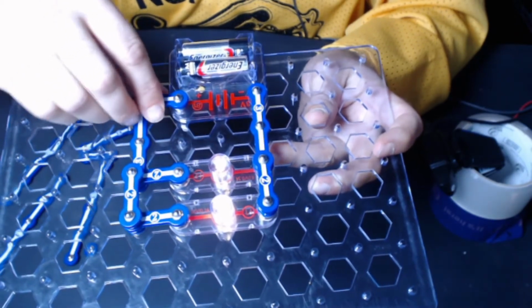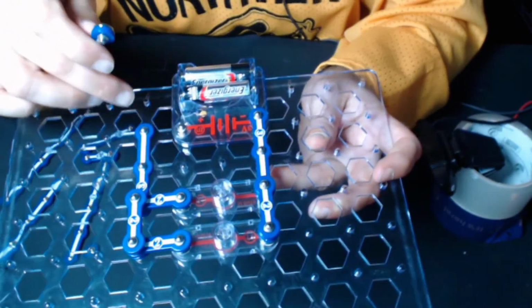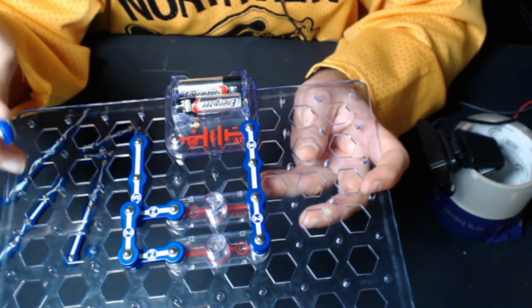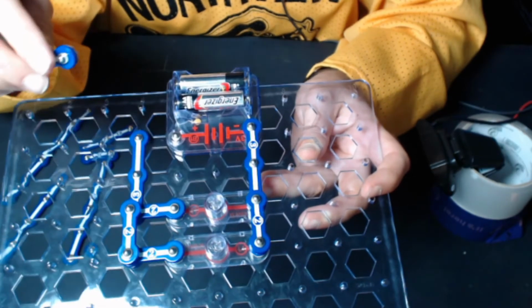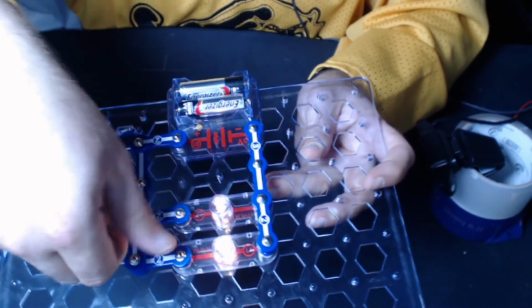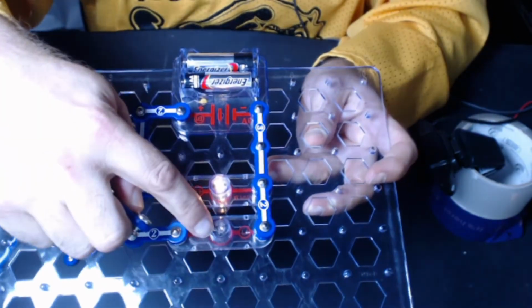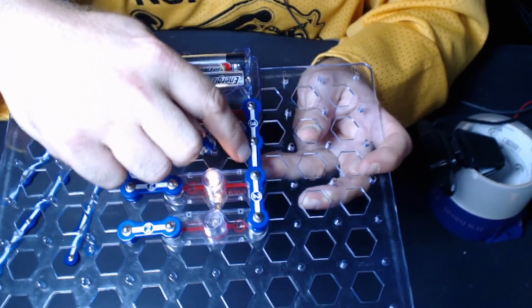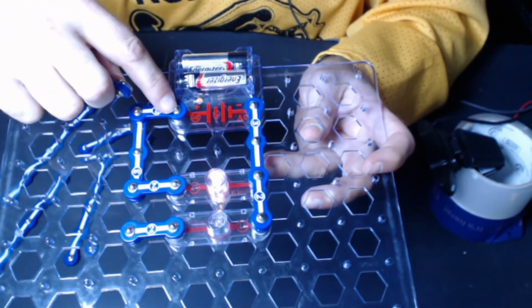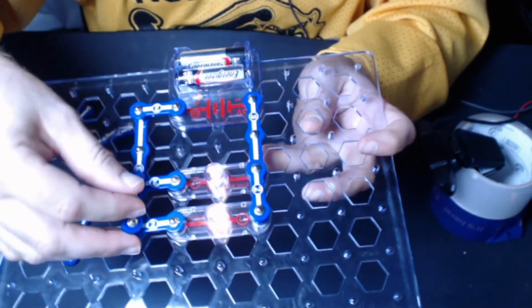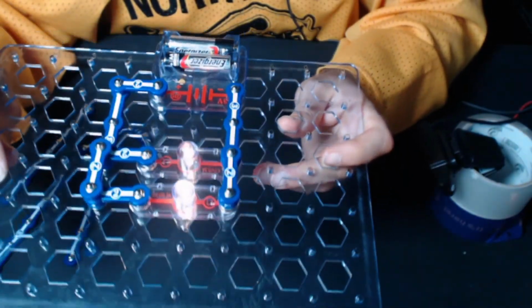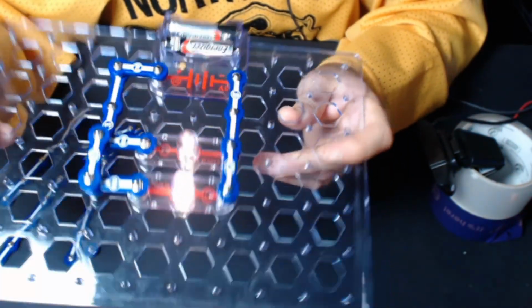Now, if I disconnect this, there is no way for the electrons to get back to the positive end of the battery. Therefore, it kills all of the electrical current going through the circuit. But again, if I just disconnect here, only that bottom light bulb is going to go out, because the electrons can travel to this junction, hit this light bulb, and then come back to the battery. So these function independently of each other. And that's parallel circuit.